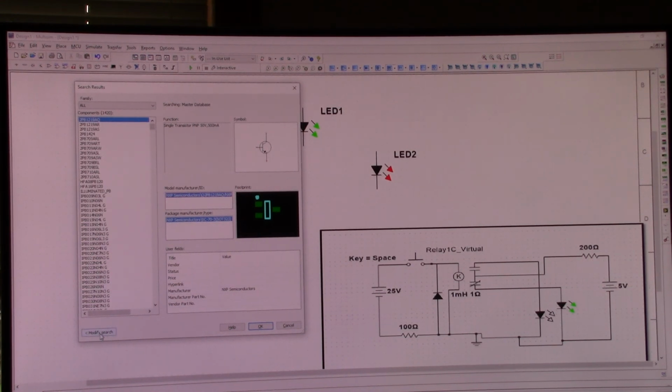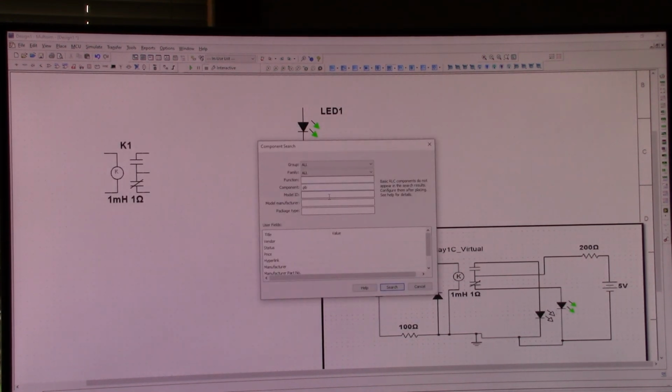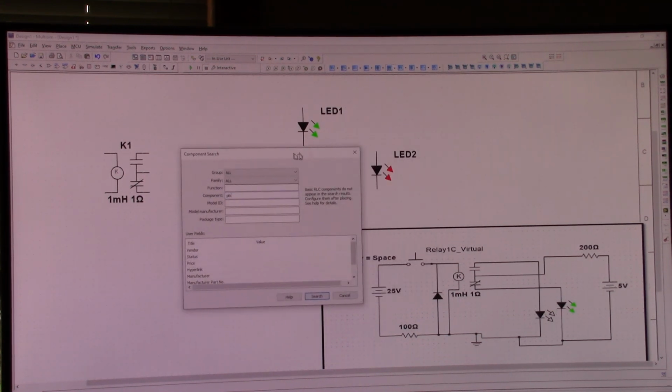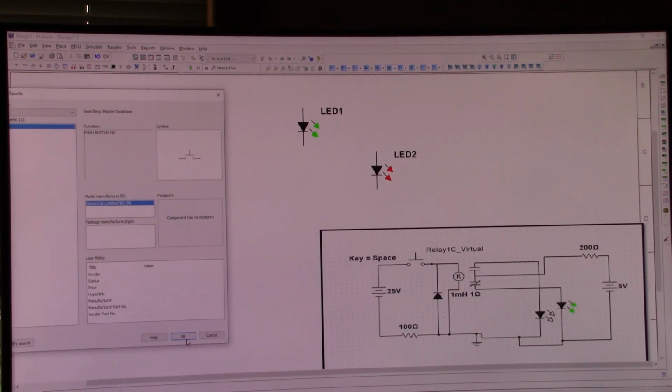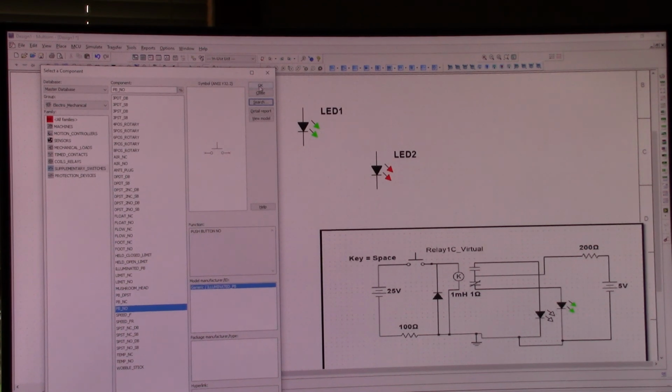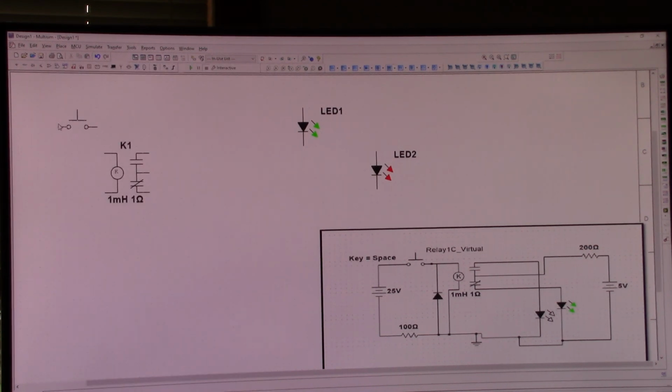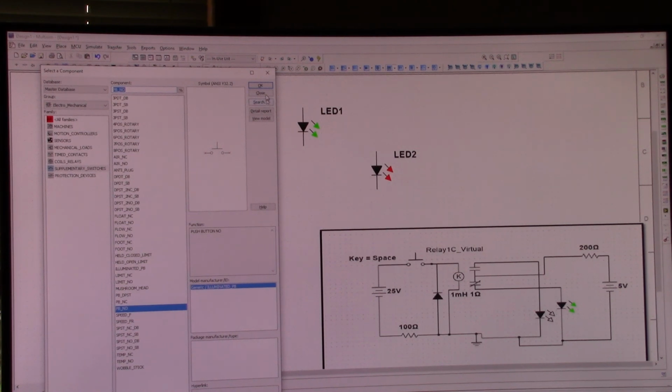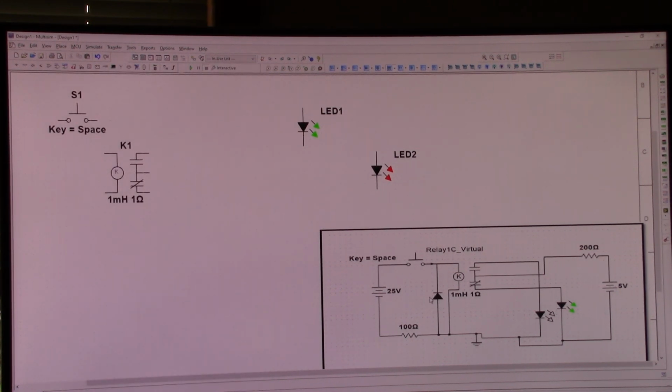So that's obvious now, we can't go through all of those, that's ridiculous. So let me modify that search a little bit, narrow it down. This is a normally open switch, so I'll just put an underscore, normally open. Hopefully that will narrow it down. There we go. And that's our switch. It goes somewhere there, right? You can build this circuit without this diode for the time being. Normally in an actual industrial situation you do need to put that diode so it protects the power supply, but for this experiment obviously you don't need to do that. And that should get you going.